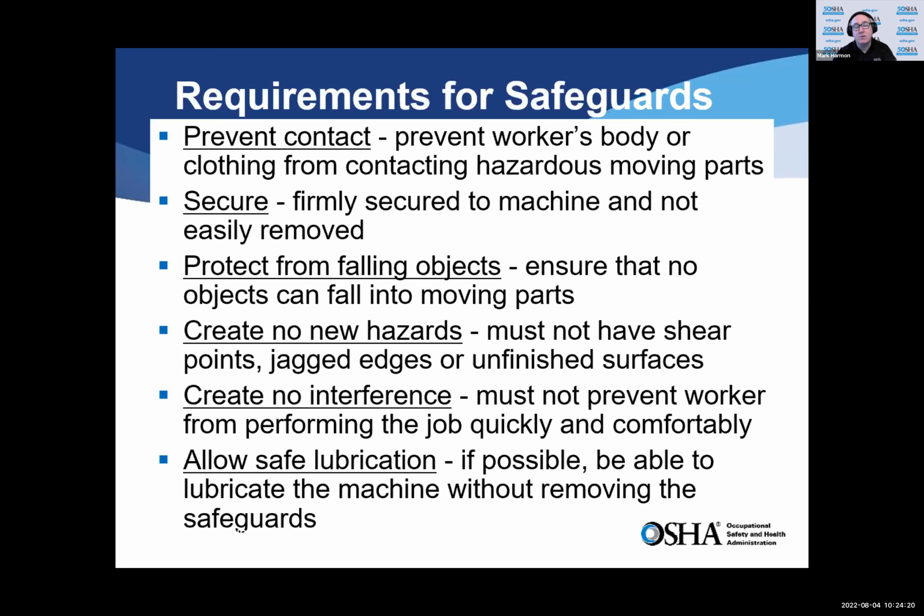The last one is also, again, very important. Allow for safe lubrication. A lot of machines need lubrication, oils, greases, things like that. Make it so that the machine can be serviced and maintained without having to put the maintenance person in harm's way. So again, questions on that, that's always a good discussion with a safety person.